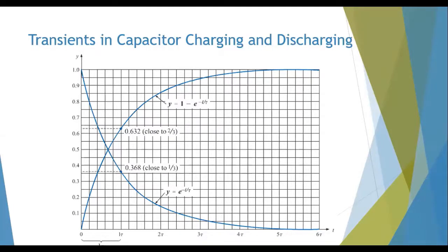So we're trying to infer after how much time we can assume that the function has reached its final value, more or less. And we find that 5 tau seems to be a proper value. 4 tau is close, yes, it is around 98%. But if you want to be closer, you would say 5 tau. 6 tau is too much, I would say, because 5 tau is enough.